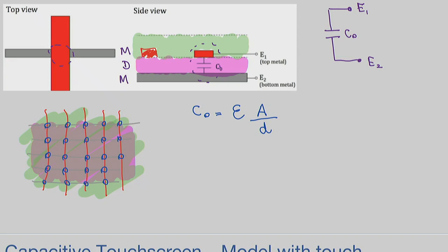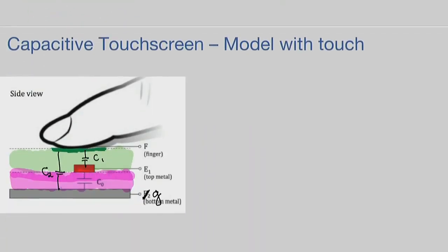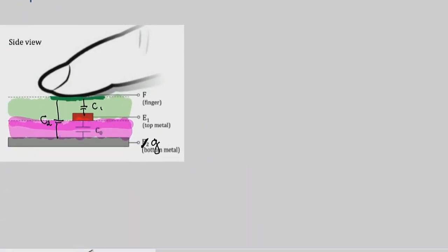That's a very good question. Actually, it's a lateral capacitor. Typically, the capacitance will be much lower than the one formed vertically because of the distance. Excellent observation. Continuing, we are going to ignore those capacitors. We are looking in the vertical.